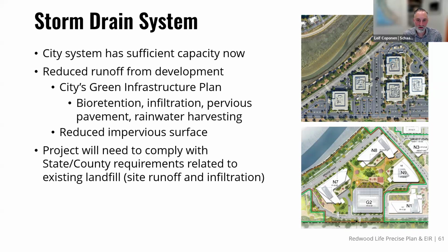The other component of it is the project plan is looking to reduce impervious surfaces, primarily the surface paved parking lots, and adding green space, which helps reduce stormwater runoff. Again, as Christy mentioned, the project will need to comply with state and county requirements related to site runoff and infiltration overlying the existing landfill. Next slide.